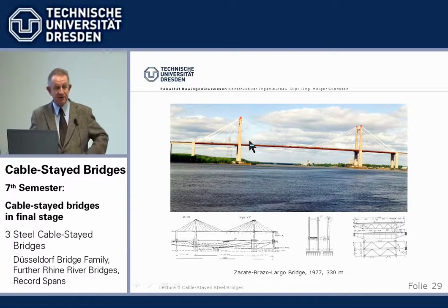Now, these hydraulic jacks, for temperature, very slow, they do not react, and so the beam can elongate or shorten between the towers without bending the towers outwards or inwards. However, if we have a rapid load, say braking of a train, then they act like rigid connections and distribute the braking forces equally over both towers.